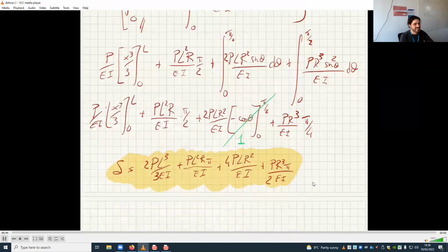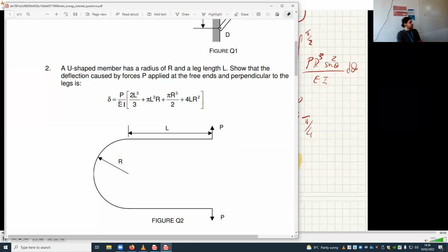Okay, so that's fine. And I was able to neglect EA because I looked at the solution, although it doesn't say, but the problem should really have stated, don't take into account any normal force. And I can see that it didn't take into account any normal force because I don't have any EA denominator anywhere.